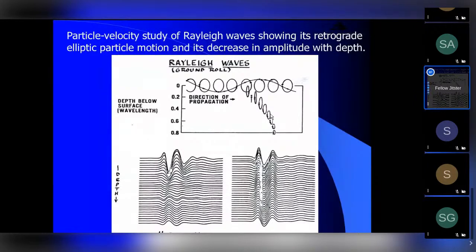Now, somebody of you may say, if this is not of our interest and it is of interest to the earthquake people, why are we bothered about the surface waves? Yes, we are bothered because this is noise to us. Anytime you are generating any wave, it generates both surface waves and body waves. You cannot stop it from creating surface waves, but we have to control them. How do we control it? We have to get rid of the noise and enhance the signal. So that's why you need to know about the surface waves.